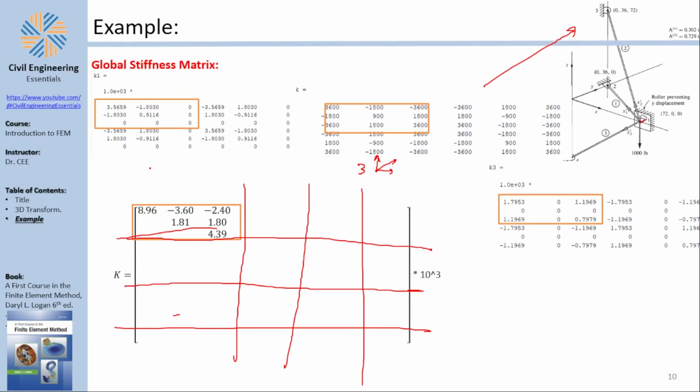Okay, now how do we think about this? Node number 1 with node number 1. I'm talking about the block now. In the last lecture, which I will link above here, we talked about U1 with U1 and V1 and so on. Now, because we're getting better at this, I'm going to just say node 1 with all its movements, U, V, and W, with node 1 with all its movements, U, V, and W. How can I find those things? Well, I need to see the elements that have node 1 in them. Now, lucky for me, all of the elements have node number 1 in them.